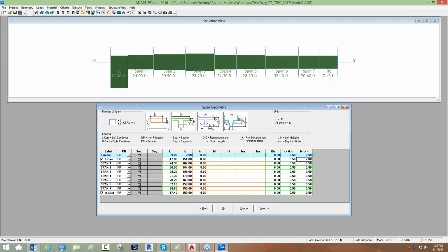So for our example, the reason we would want to change this, it doesn't affect the analysis, because the analysis is just a simplified two-dimensional frame. So we're considering flexure and shear. We don't consider any axial restraint or axial deformation. We don't consider any out-of-plane bending. That's the purpose of the equivalent frame method, to simulate what the response of the frame is if you were to model it, for example, in a 3D or maybe a finite element frame or a skeletal frame.